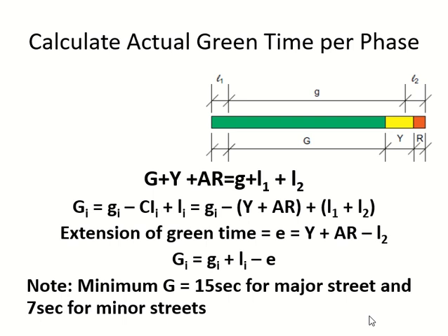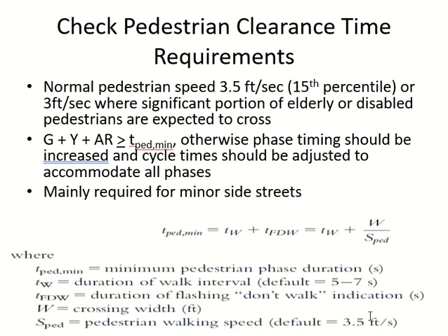Okay, so it will not give him enough time to react. Any value less than this is not practical for the driver. It will be too sudden. Some of you have done the speed studies for the project, right? If you did it using the time, 2-3 seconds the car will move and you will not even know it. So we have some practical restrictions.